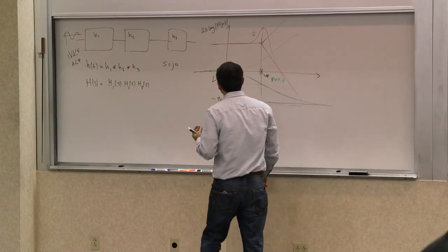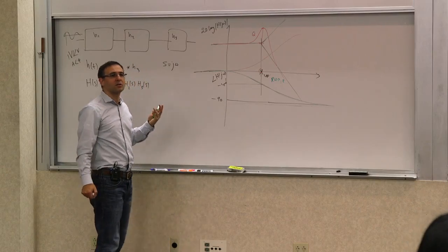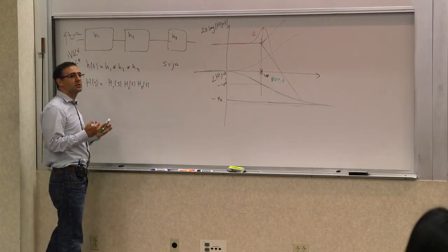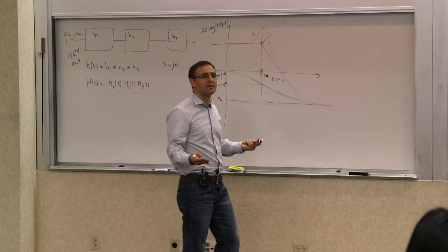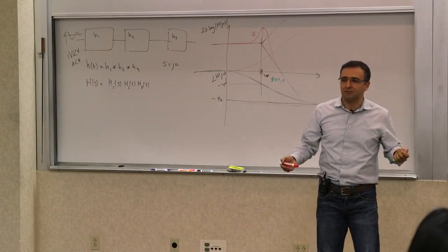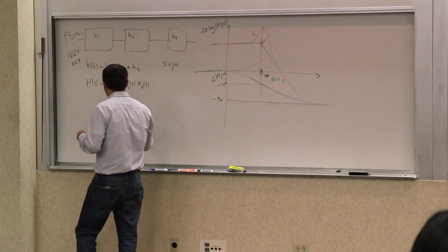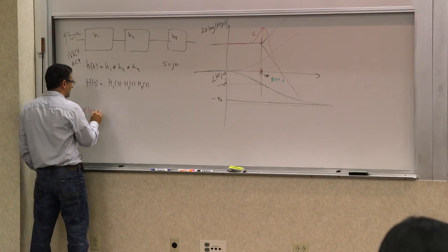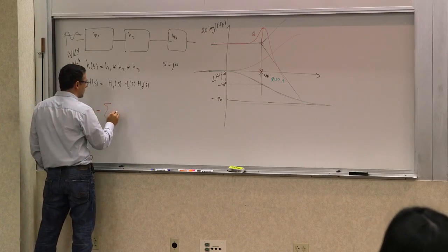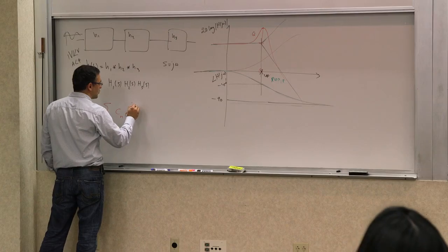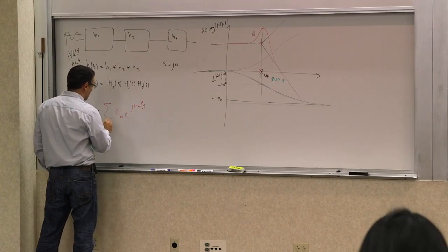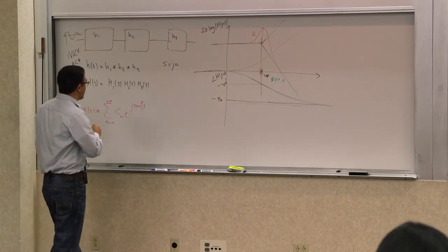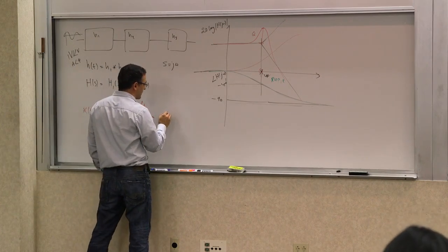So now the last thing we did was basically looking at the Fourier transform. We took the Laplace transform and we looked at it on the j omega axis, or conversely, we took the Fourier series, which allows you to write a periodic waveform as a sum of exponentials, or cosines and sines. So you could, in general, write it as e to the j 2 pi n f naught t, for n going from negative infinity to positive infinity. And we saw that eventually that corresponded to the Fourier transform.